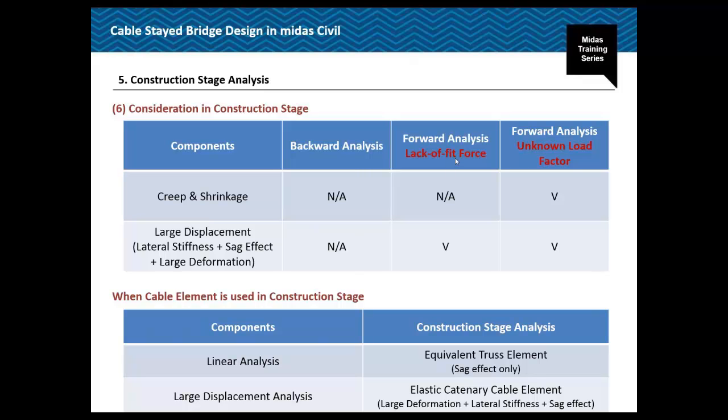But if we think about the Lack of Fit force, the Lack of Fit force could consider the large displacement, but not the creep and shrinkage effect. Unknown load factor could consider both of them in the latest version.